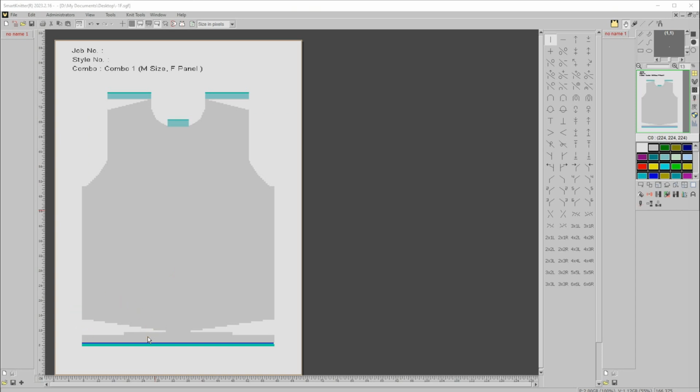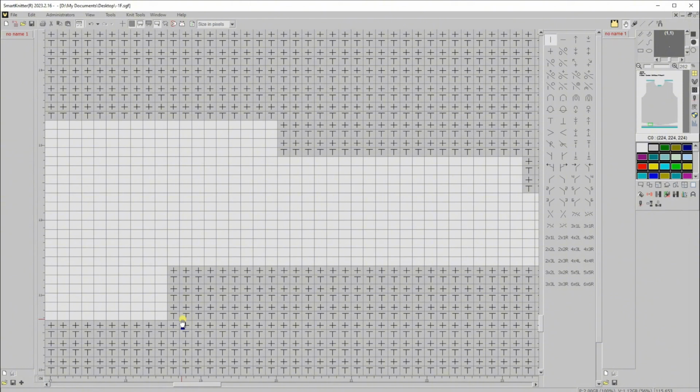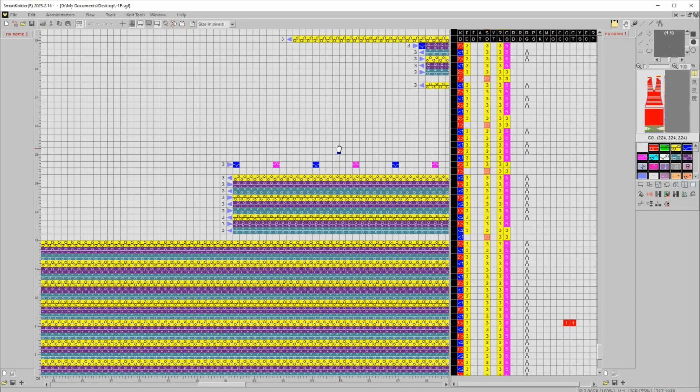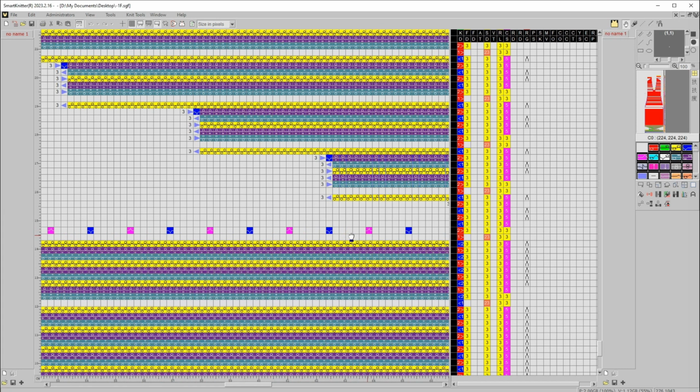Tool 8, Split Tubular into 2 lines. Tubular is represented in 1 row in knitting instructions. This may cause the carriage direction for partial knitting to be incorrect while exporting to machine code, as shown. There are extra floats here.